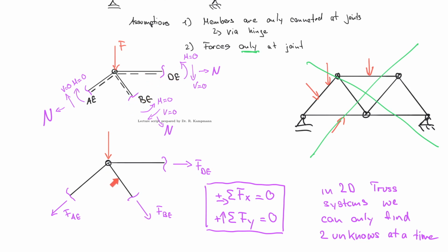For now, it's important that we made the jump from internal forces here to only normal forces. And the reason for that is this condition, that we only have forces at the joints. That means that the moment goes to 0, the shear force goes to 0. And that is something very pleasant because we have dealt with this actually before in this class, the sum of the forces in x being equal to 0 and the sum of the forces in y being equal to 0, and only finding forces along a member axis.